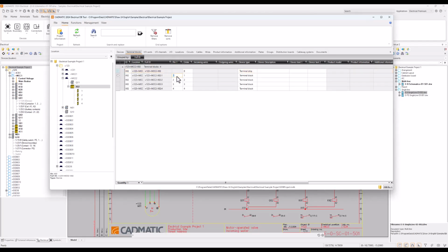And now you just change the pin number to L1, L2, L3, not my day today, L3, and the protective earth. And it's a bit quicker way to do it, to have those blocks inside the terminal. But anyway, there are many ways to create these blocks. And then the last thing we want to create is, maybe you select the MCC2, go to cables.